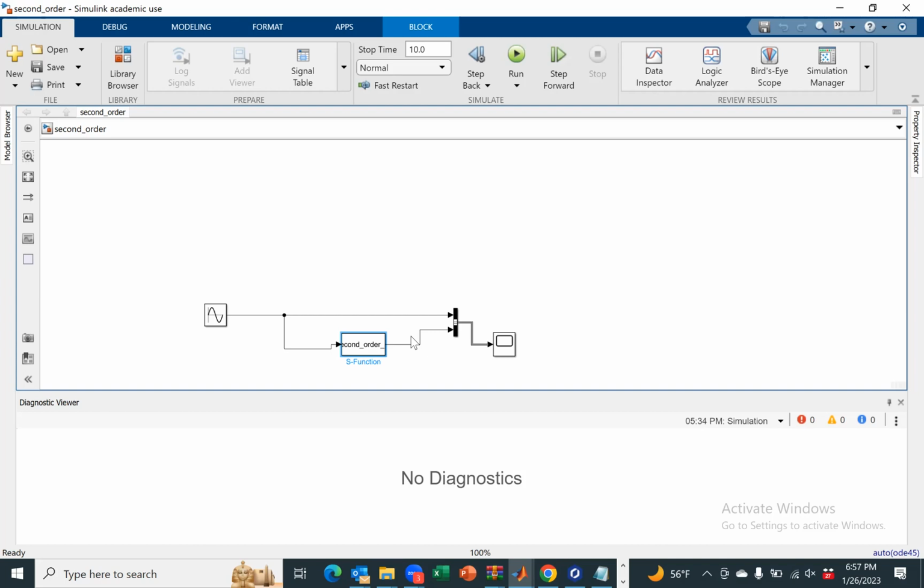We looked at the eigenvalues, stability, all that stuff. At the end, if I want to solve this expression inside MATLAB using ode45 or ode23, what is the first step I need to do? Define symbols. Convert that equation into a first order differential equation, remember, into state space form.